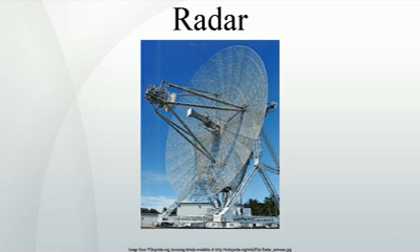Slotted waveguide. Applied similarly to the parabolic reflector, the slotted waveguide is moved mechanically to scan and is particularly suitable for non-tracking surface scan systems, where the vertical pattern may remain constant. Owing to its lower cost and less wind exposure, shipboard, airport surface, and harbor surveillance radars now use this approach in preference to a parabolic antenna.